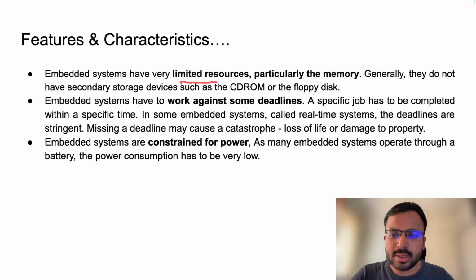Why? Because the memory present in these embedded systems will be small, because memories are costly. You cannot have large memories attached, because then you are making the embedded system itself costly. So the memory size will be small and the code footprint will be smaller. That is one very unique feature of these embedded systems. And of course, you need only smaller memories and a smaller code footprint because it is only performing one specific set of functions, not many functions.